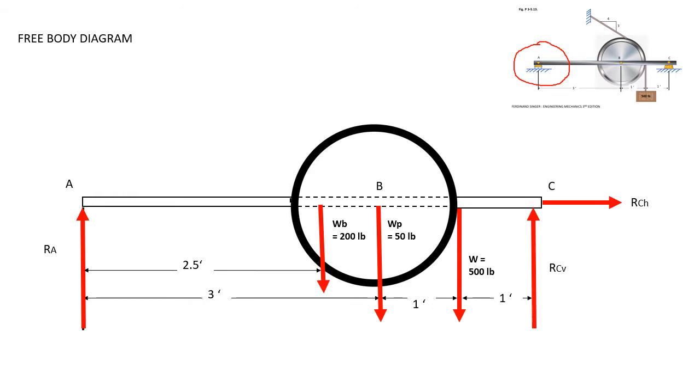So we proceed to point C, notice that at point C we have a hinge support. A hinge supports forces horizontal and vertical. So also, just like the reaction at point A, we assume that it is pointing upward, and we assume that the horizontal reaction at C is pointing towards right.